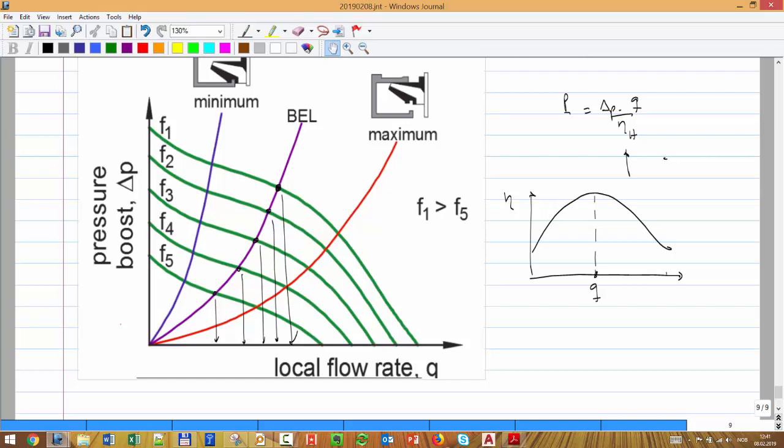Now, these two lines are related to what happens with this floating impeller. If you float too much to the right, then that impeller will be pushing to the back, because the flow is just too high, and then you will have a lot of erosion on the back of the impeller, what you have there in your hands. If the rate is too low, that means the impeller will be laying too much weight while it rotates on the lower part, and then you will have too much erosion. So that's why we define these two lines, which is the line of up thrust and down thrust.